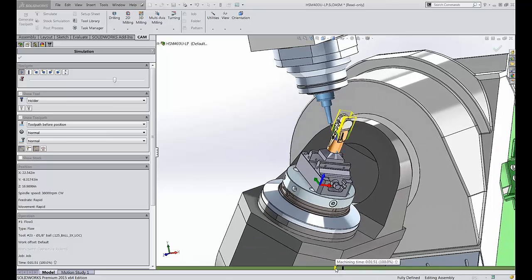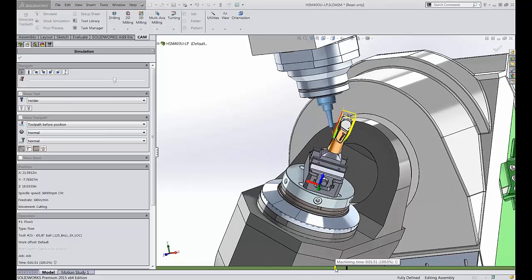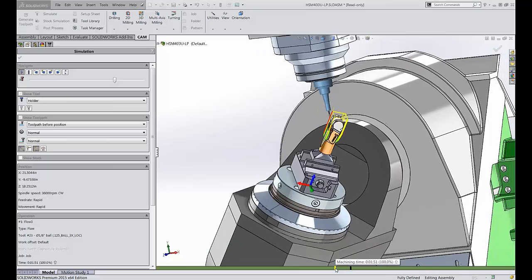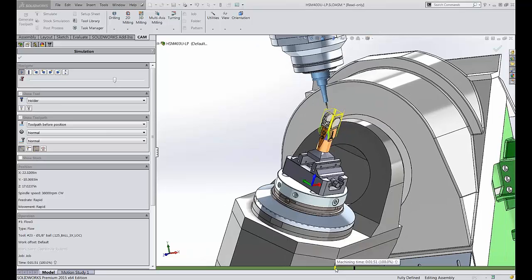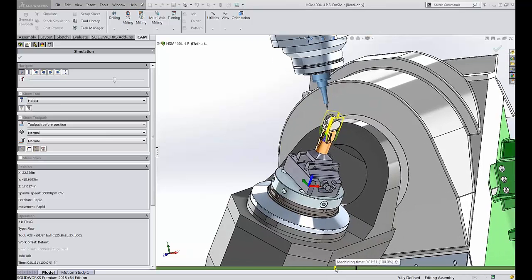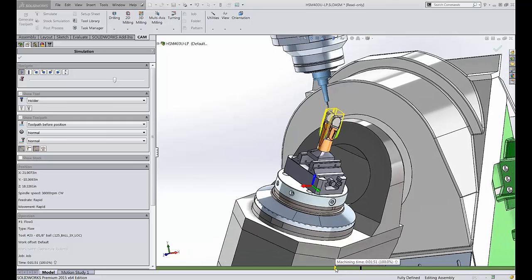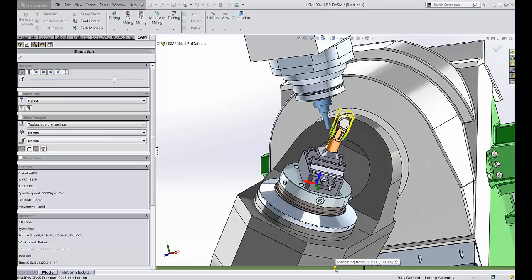Right, and I should add, even if you do have machine simulation, that is a very, very useful trick. The reason is that then you can use the entire spindle to check in Toolpath. So then your Toolpath can avoid your spindle rather than just finding out that it's going to crash and then not having any way to do anything about it in the Toolpath.